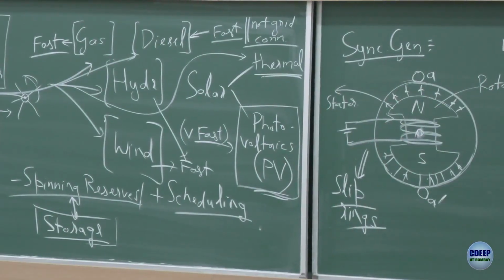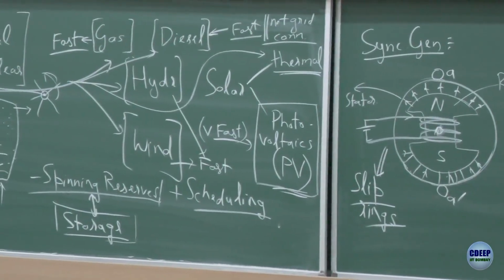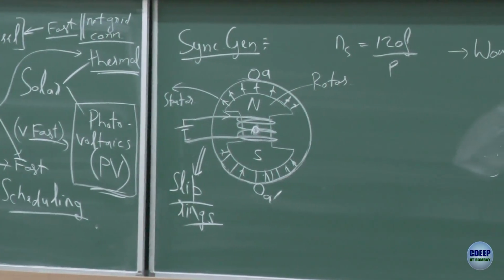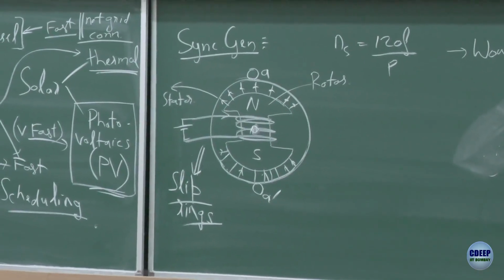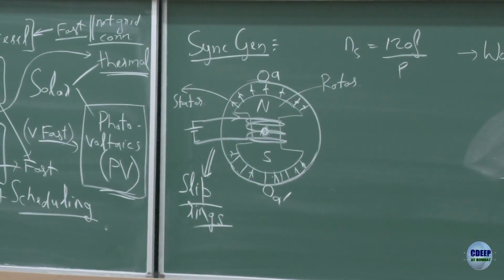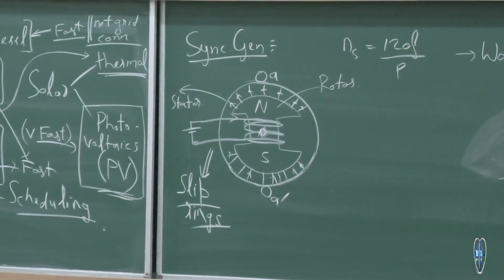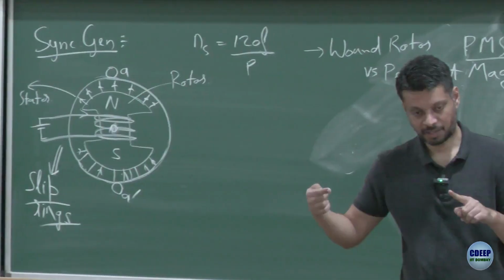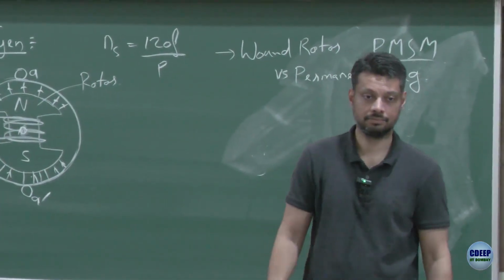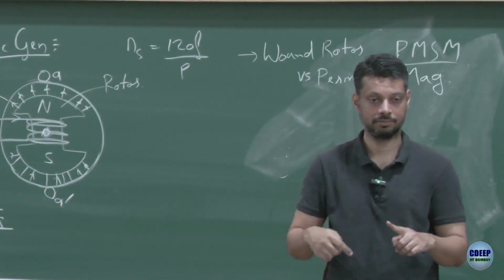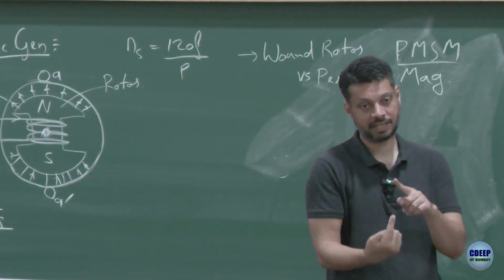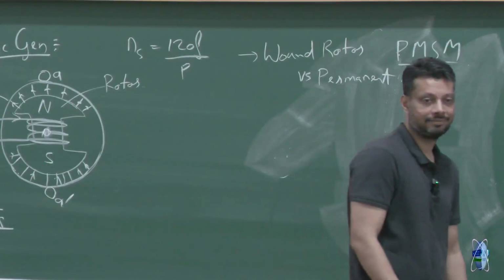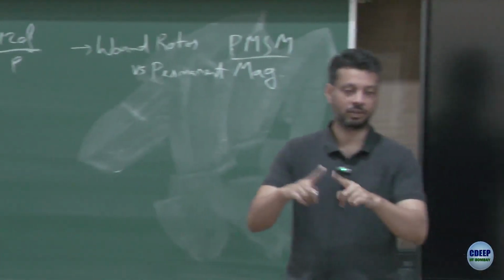The field will never complete the circle. That's why we are putting slip rings. So they're connected before, and then you move this and connect again there. You take the wire from inside the rotor and connect it. Don't take it from outside the rotor. The rotor is hollow, so take it from inside and connect to the slip ring. You can do it. Your wires will not cross.